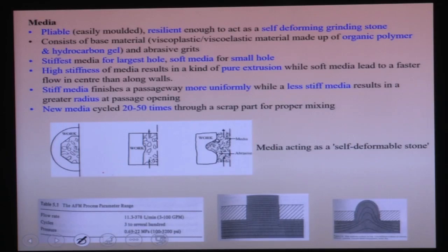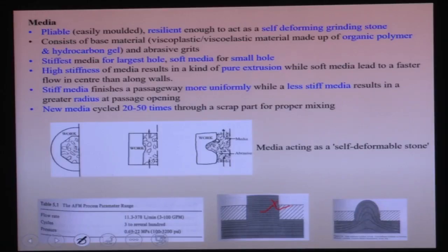The stiffest media is used for the longest holes. Suppose you want to polish long holes. In that case you have to use the stiffest media, because, as you can see in this figure, if you use the stiffest media, the media velocity will be uniform at every cross-section.